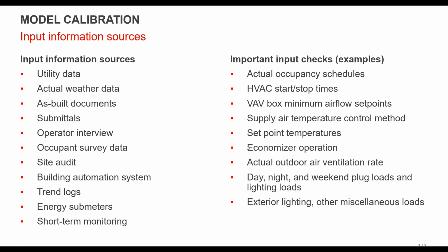Usually the economizers don't work so well. The dampers might be leaky. So getting a good understanding of that, and then looking at day to night, right? And sometimes we like to look at the sub-hourly data and see what happens over a typical day. Those sorts of schedules will help define the inputs that go into the model.